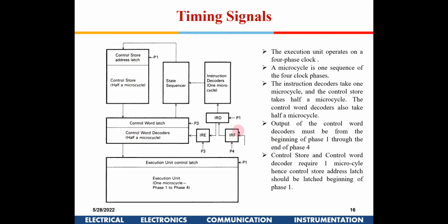That PC value corresponding to 2 microcycles should be placed here to give it adequate time to get decoded here. So accordingly you will find that the instruction fetch has to be incremented and placed in advance. The PC count needs to be placed here in advance.